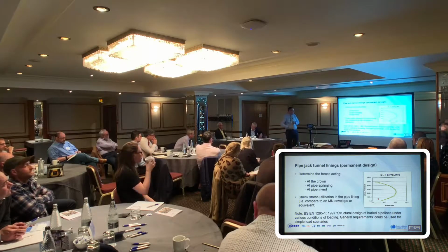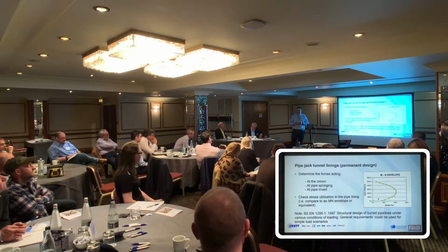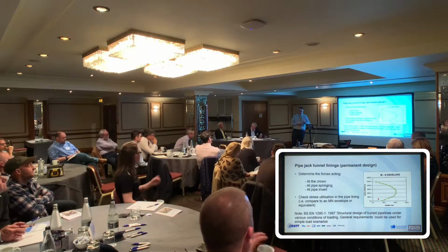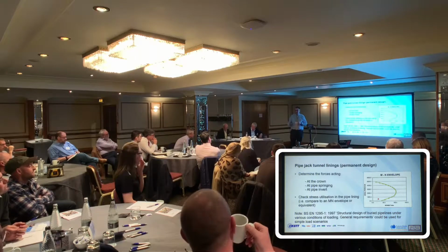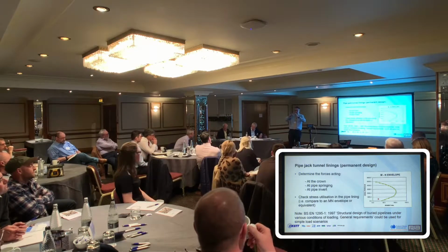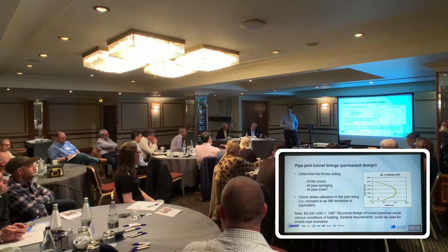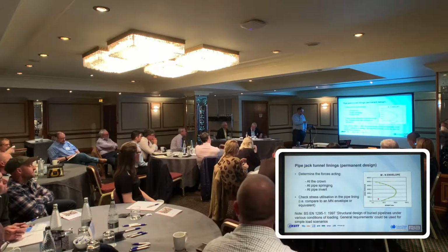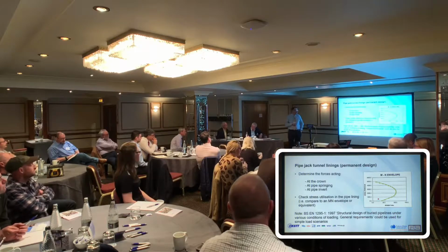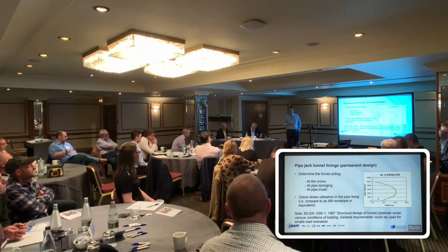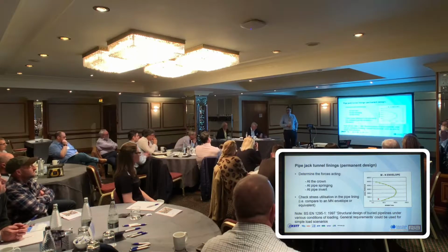Now, its sister document, which I think is 9295, off the top of my head, does have a very, very small section about pipes that are installed by trenchless methods. In short, for those of you that are familiar, in terms of the pipe bed, it comes in classes, and a fully encased or fully surrounded, well-supported bed is a Class S. That standard tips its head towards that, but I would certainly recommend that for more challenging jobs, perhaps if you're deeper or in very poor ground, you should be looking at it in a little bit more detail.